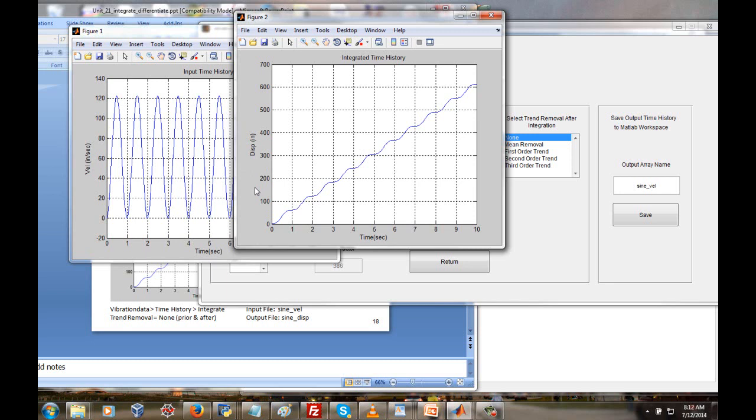Now in reality, once we get into the measured accelerometer data world, things can actually be a little more complicated because sometimes that accelerometer data can have a little bit of a spurious low frequency trend, or the data can just drift around a little bit due to different measurement imperfections. So whatever drift is going on with that accelerometer data, that will affect both the velocity and displacement.